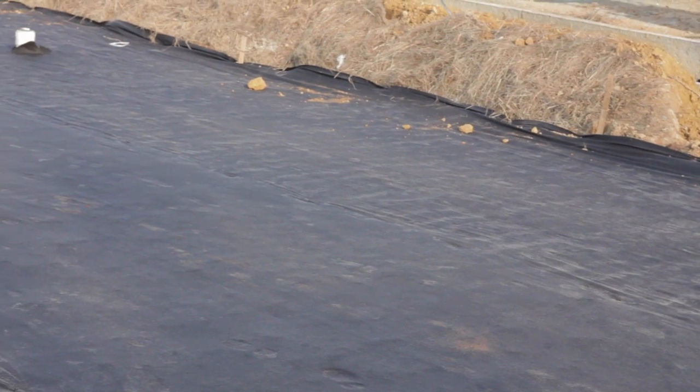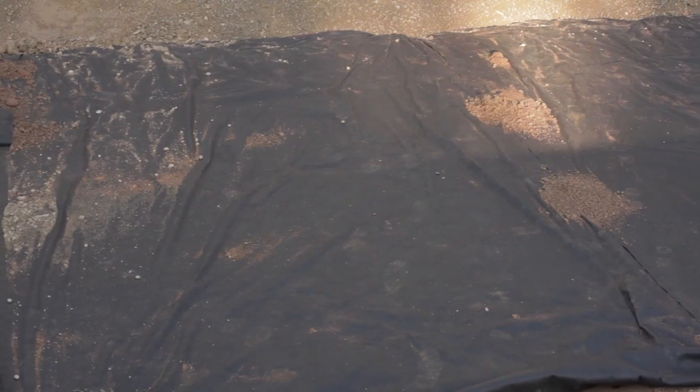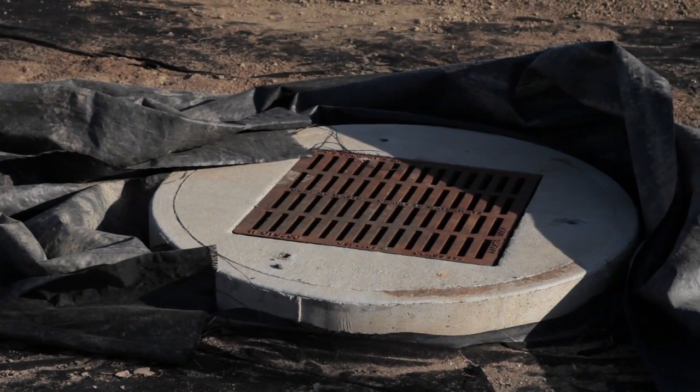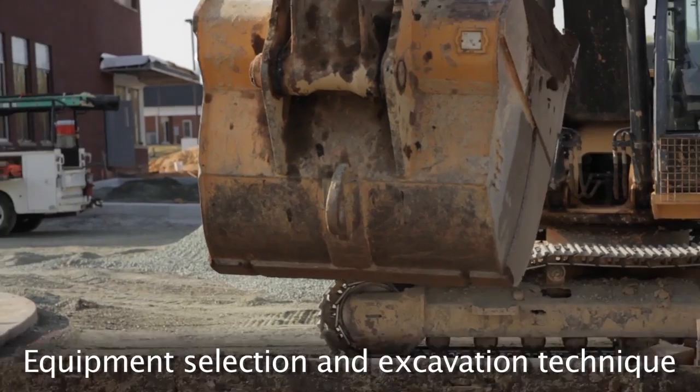So what we try to do is we put a protective layer of geofabric over, so if we have any washing rains, and again, you're going to have sediment wash off the slopes, any sediment that's washed in will be captured by the fabric on top, which will be removed before it's all finished and final graded at the end of the job. Next, use the appropriate size and type of equipment for the job.